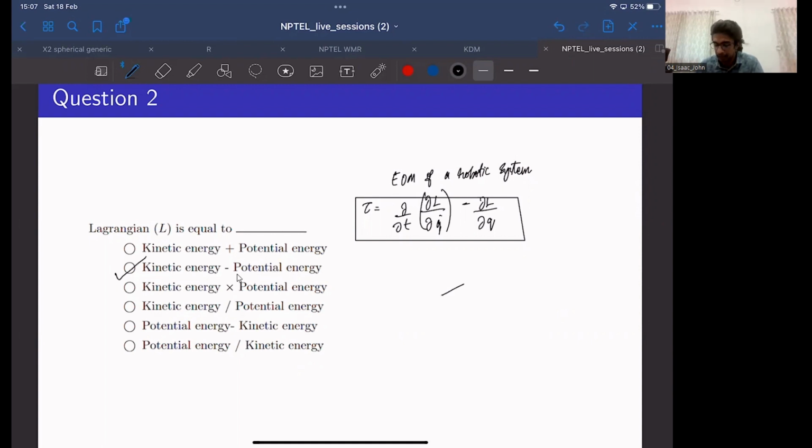If you consider a land-based mobile robot, it will operate only along a plane. So if you consider this plane as a datum, or the reference where the potential energy is zero, the potential energy would be constant throughout this entire datum. So in that case, you can consider potential energy to be zero in case of a land-based mobile robot. But in case of a general robotic system, maybe a spatial robotic manipulator or underwater vehicles, Lagrangian is defined to be the difference between kinetic and potential energies.